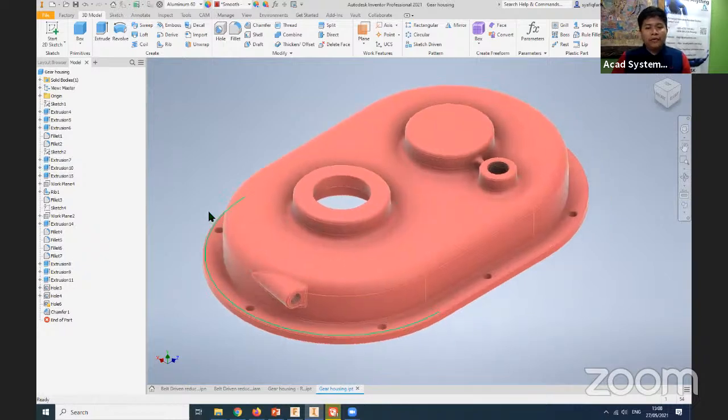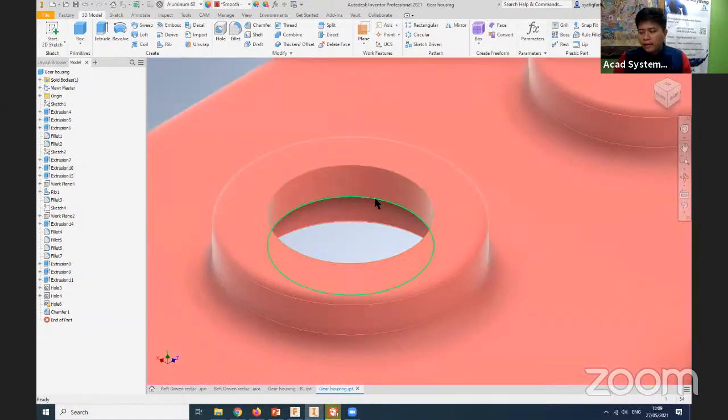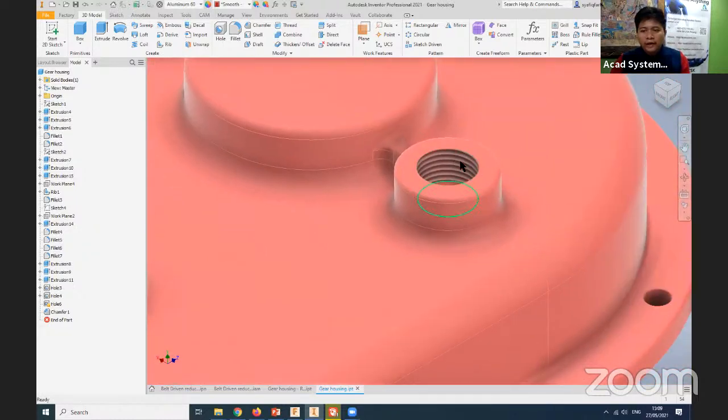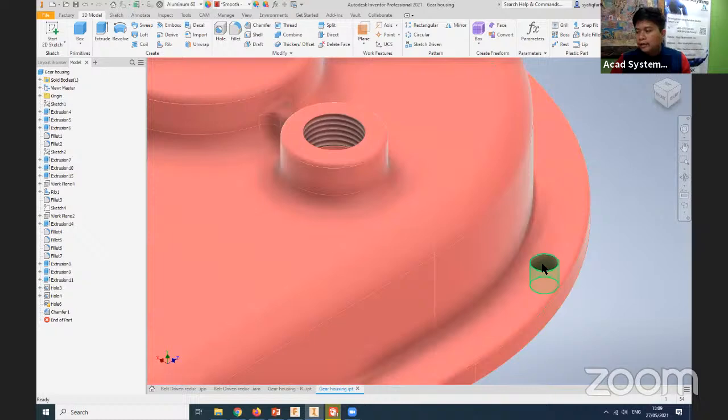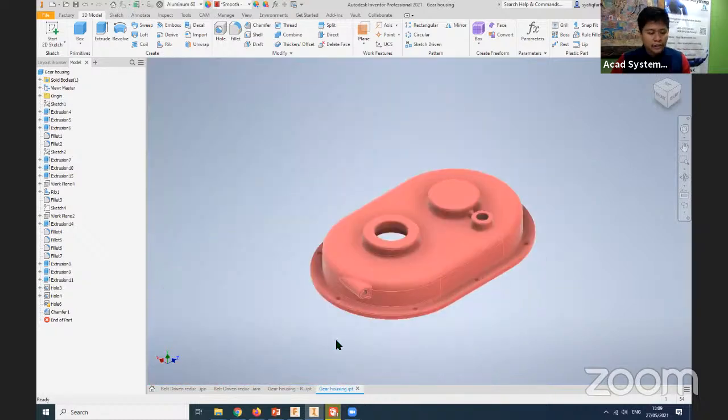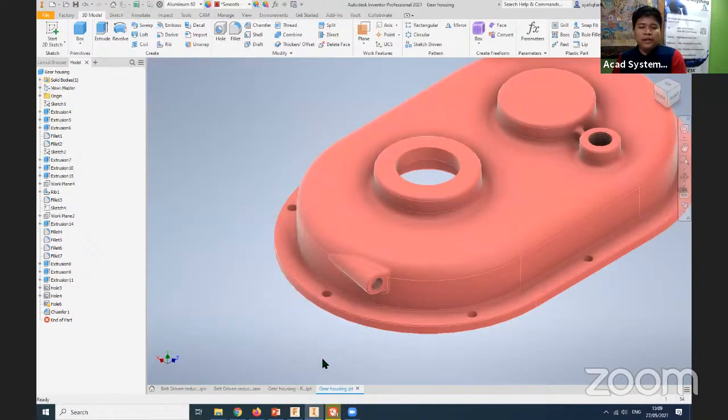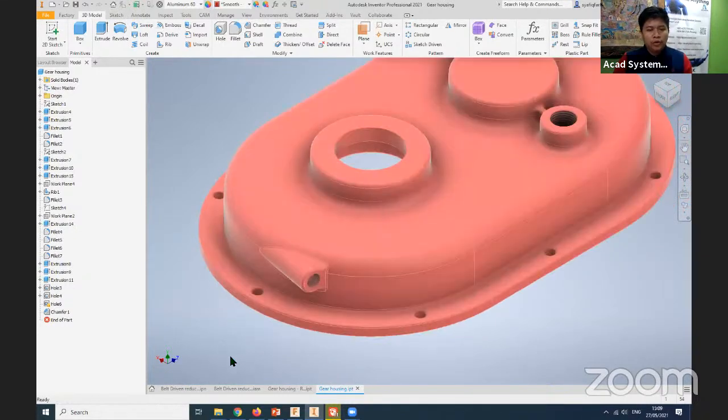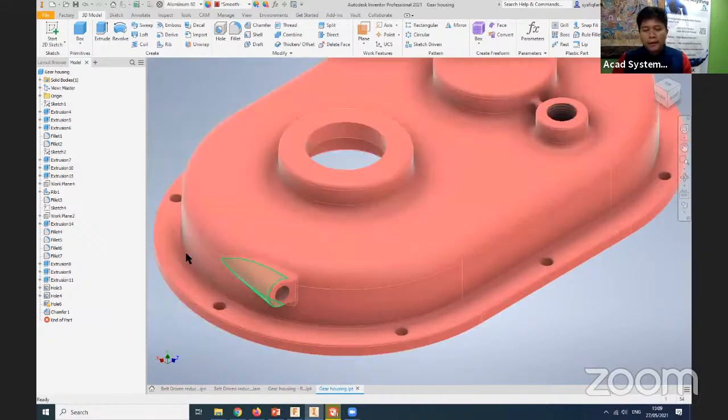The problem in your drawing, after you insert the material and also the appearance, is that you will see this area, which is focused on processing afterward, and this area, and all the holes. So how can I change the holes to a new appearance? I just need to select them manually, one by one, 1, 2, 3. If you create your model with a proper project tree, you can select directly like this, 1 until here.